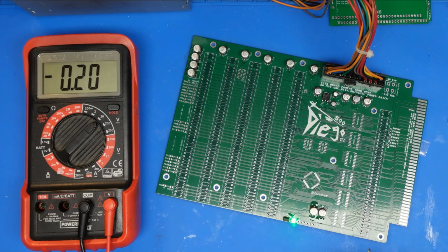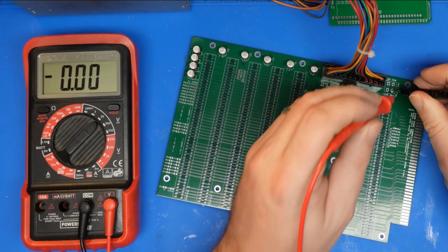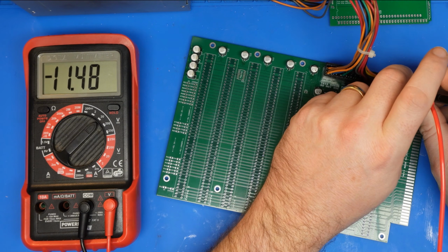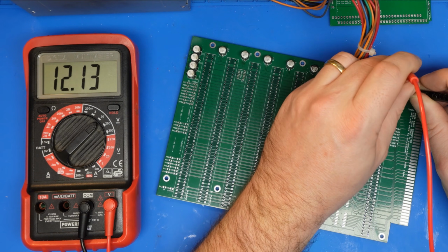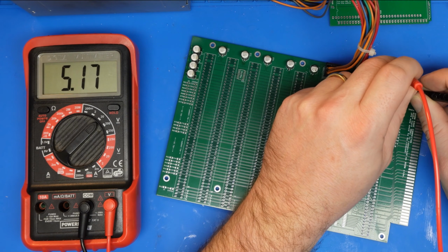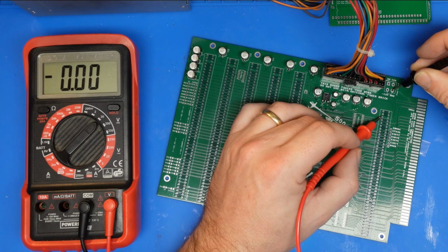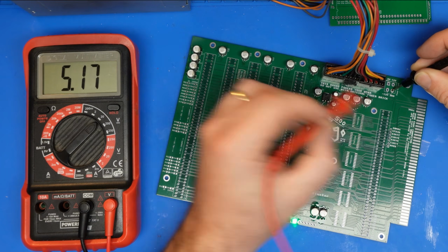So let's just quickly test some voltages across this board. Starting up here at that pass-through power connector. So ground is there as labelled. Just beside ground is -12. And yeah, that's right. And above ground is +12, also right, and then 5 volt. Yeah, that's fine. Now we should have 5 volt here on the coprocessor slot, which we do on those 2 pins.